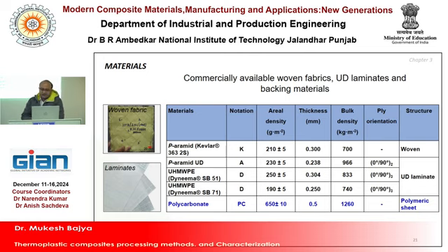So these are the aramids, para-aramids. You heard the aramid terminology in the last 2-3 days. But there are different aramids, para-aramid and meta-aramid. Meta-aramid is generally used for fire protective clothing, and para-aramid is used for impact resistance applications, because it has higher strength and modulus. In the case of meta-aramid, strength is lower as compared to para-aramid because of their chemical structures.